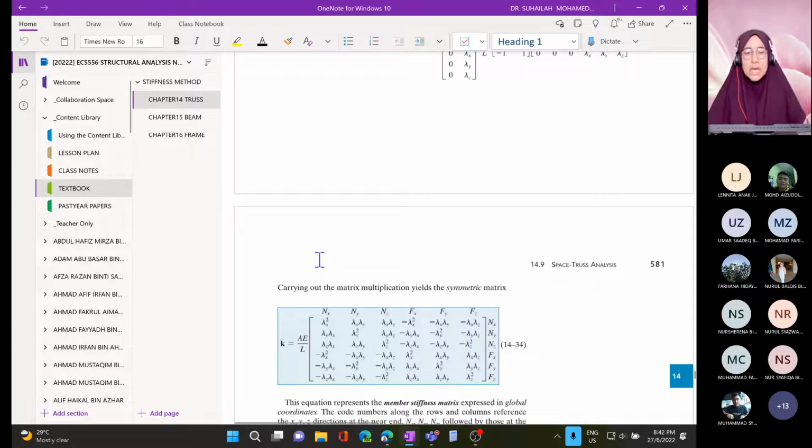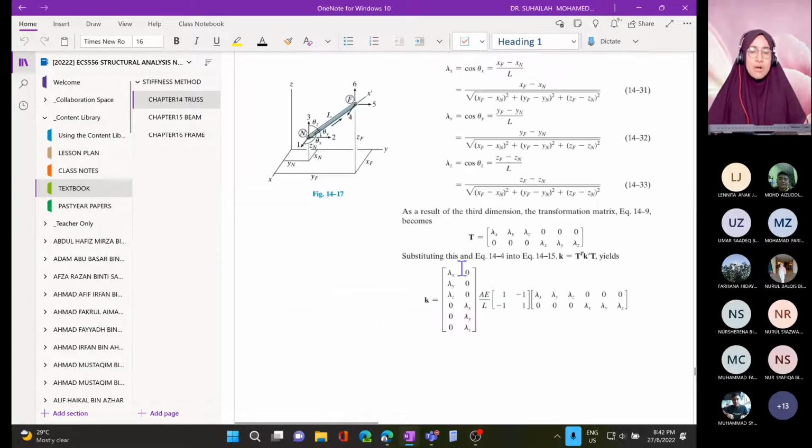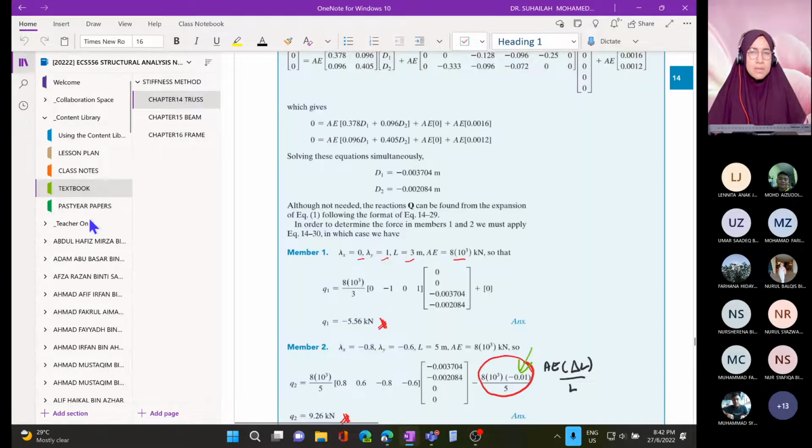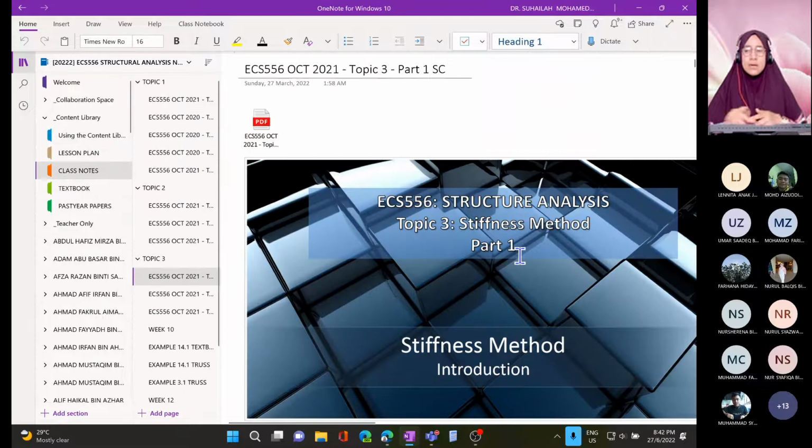That is the most important thing, because the degree of freedom relates to the force Q. Because when we want to solve the displacement and forces, we will use the stiffness equation, and the stiffness equation is actually Q is equal to KD. Okay, we will look at that. It has a physical meaning that every student needs to understand, so that you don't need to remember.